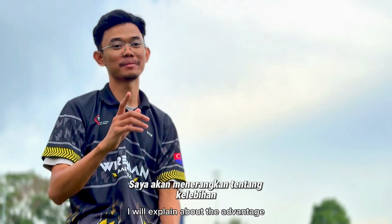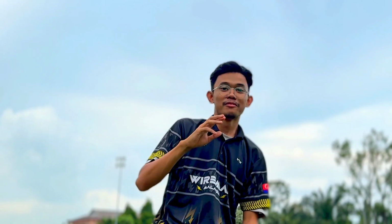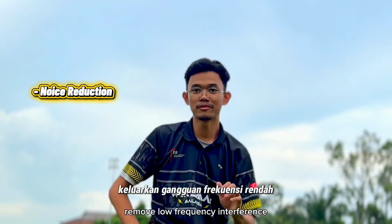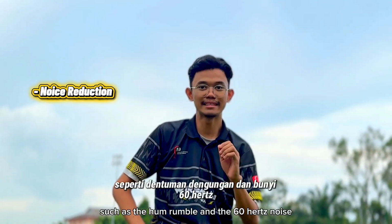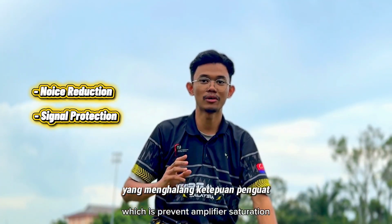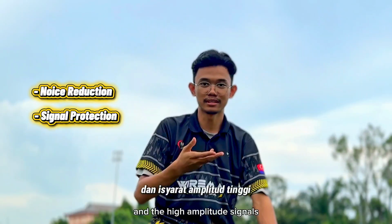Okay, next I will explain the advantages and disadvantages of the high pass filter. For the advantages, the first one is noise reduction. High pass filters effectively remove low frequency interference such as hum, rumble, and 60 Hz noise. The second one is signal protection, which prevents amplifier saturation or speaker damage from excessive low frequency and high amplitude signals.